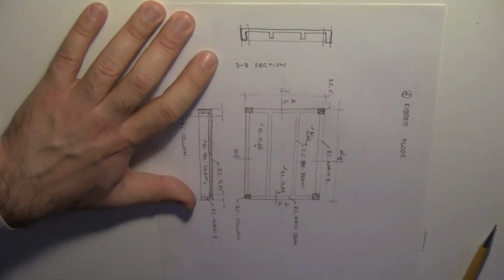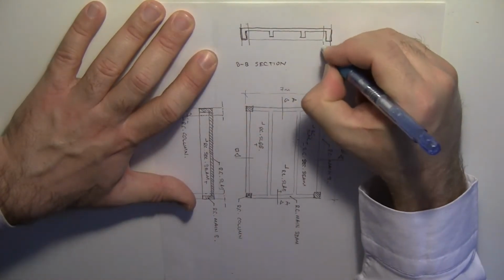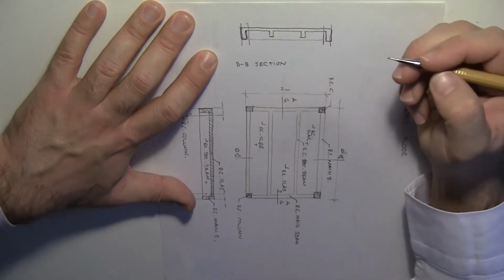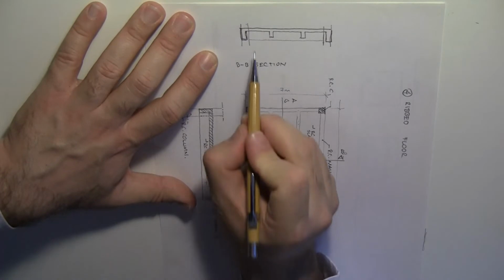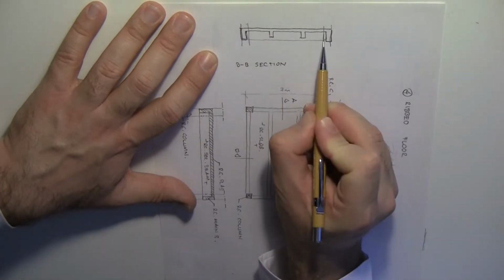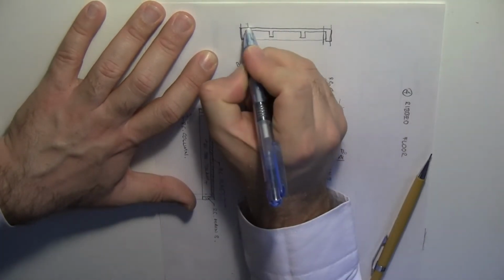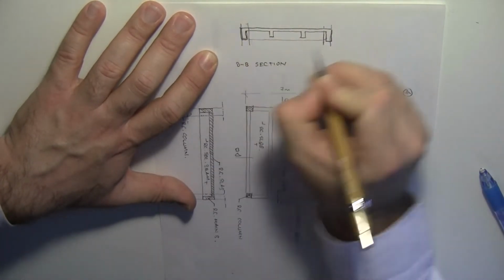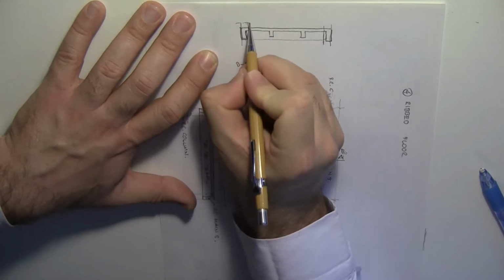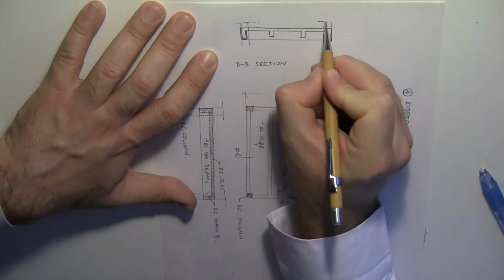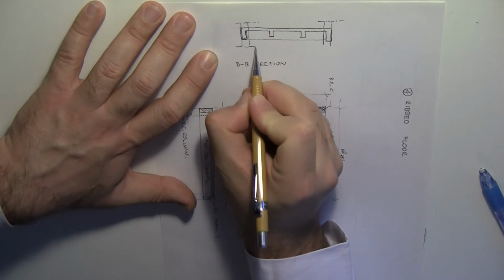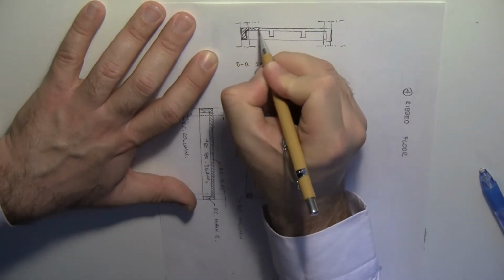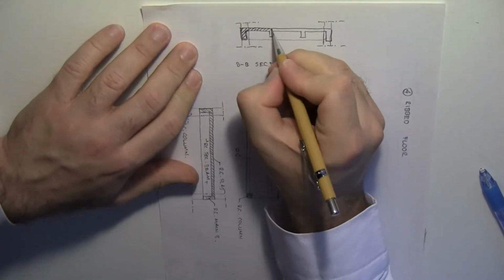That's the main beam. Be careful this time. I am not going to tie the main beam to the other main beam here, because main beams are tied to columns. So I end it here and there. I'm going to erase this line and that line there, and transform them to dashed lines like this. Dashed and dotted line here, dashed and dotted line there, dashed and dotted line here, and one more there. And I will hatch the reinforced concrete part of it.